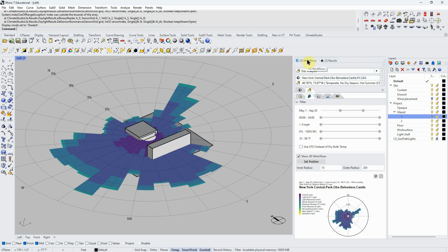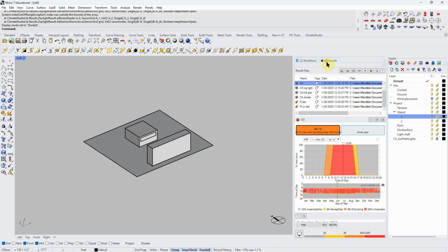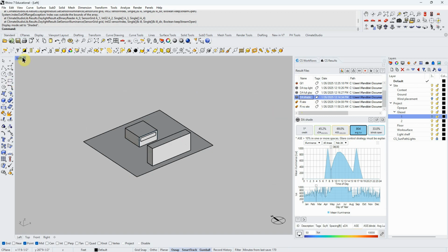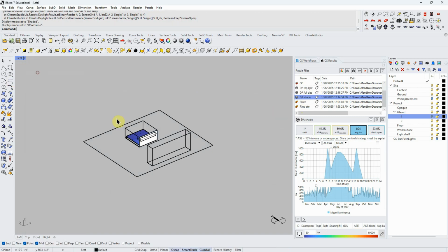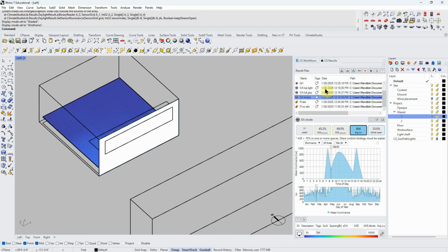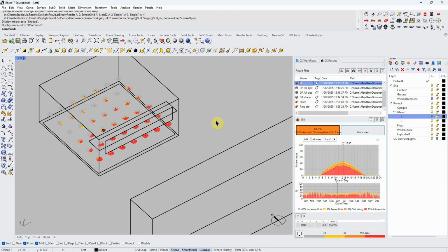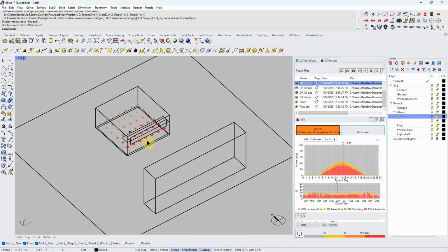We did site analysis, wind and sun. We did radiation maps and talked a little bit about how those work. We did daylighting analysis, where we're looking at how much daylight is coming into a building as opposed to heat, and we looked at glare.